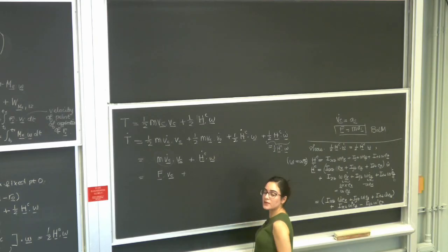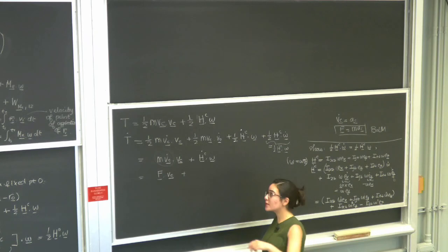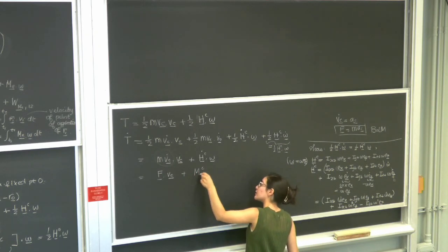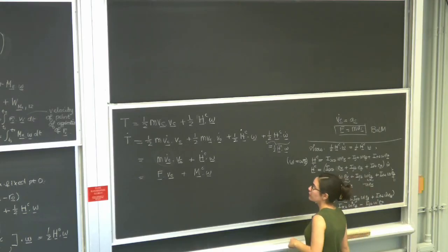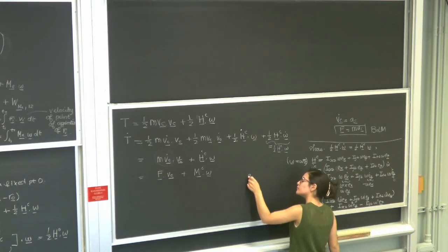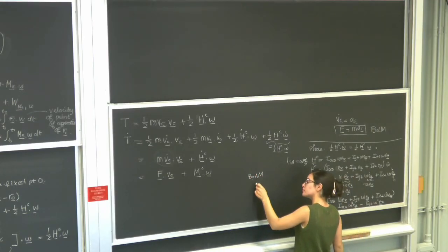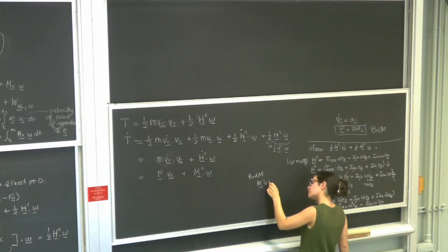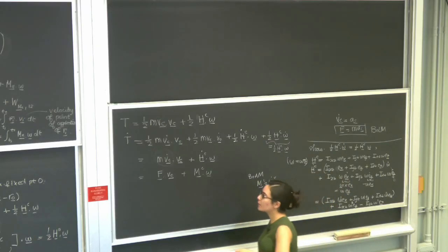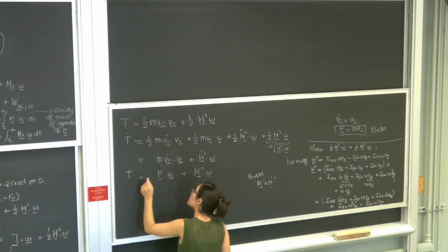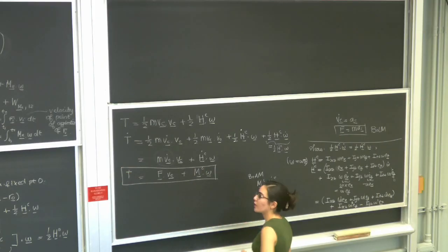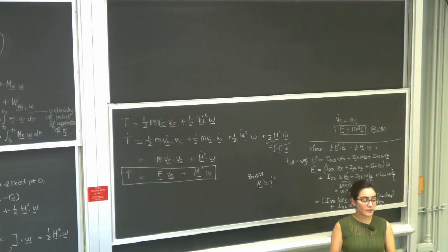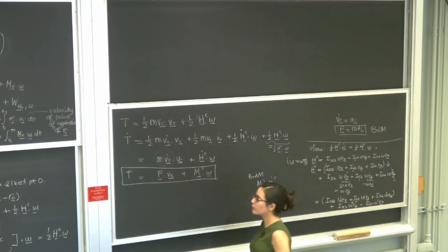And what is H dot C equal to? M_C from the balance law, the balance of angular momentum. Okay, from the balance of angular momentum, I get this. And this is my work energy theorem. Okay, and I can integrate this to get the form you're probably more familiar with.